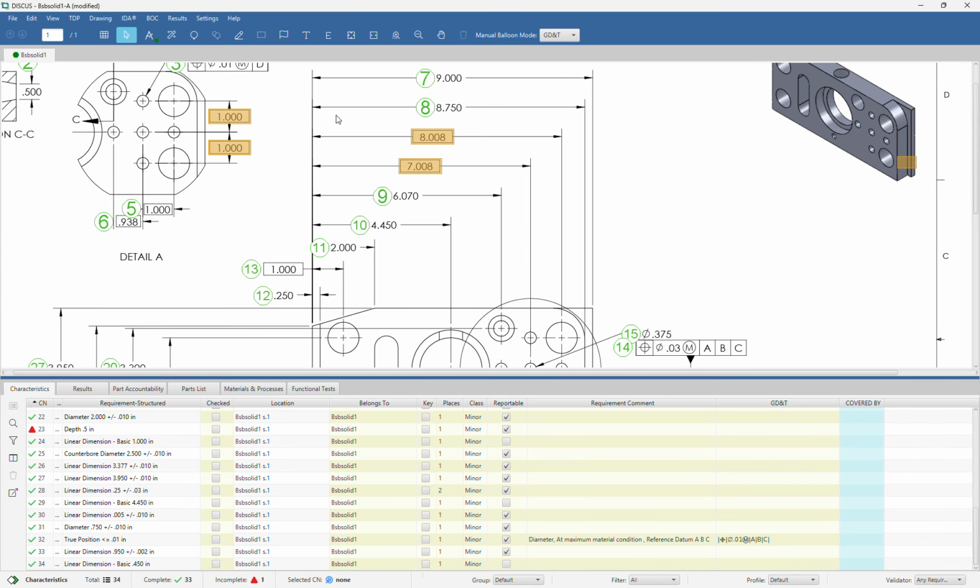We can zoom in, and I'll hit Control W, which is a virtual whiteout, and I'll show you what it's going to white out. You see these requirement images. It's essentially that containing box around the dimension. Well, we're going to be removing that. So we'll hit Control W, and now all of the requirement images have been removed. Control W again to bring it back.